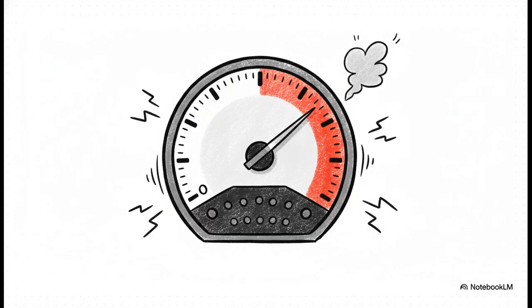Okay, so one of the most dangerous and honestly most common mix-ups out there is confusing design pressure and operating pressure. Someone might see the design pressure on a spec sheet and think, great, we can run the system at that level. But no, that's like driving your car with the engine constantly at the red line. Sure, it's designed to handle it for a short burst, but it's not meant to live there. Doing that just completely erases your safety margin.